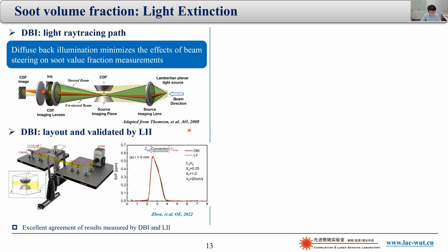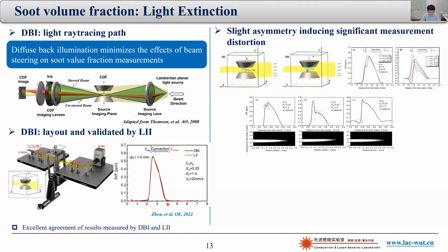In a recent work, we performed the first DBI method study in counterflow flames, and we achieved excellent results that can be confirmed by our LRI measurements, which I will discuss later. You can see this DBI method as compared to LRI is almost a complete overlap, confirming the validity of both methods. However, there are also complications for this method.